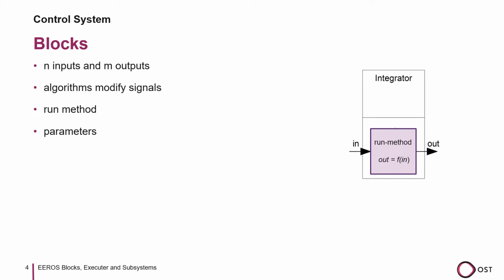The example shown on the right is an integrator block. It is often used to build PID controllers or to realize observers. Sometimes you also want to save values and use them the next time the algorithm is called. In the case of the integrator, this is the integrator's internal value. Blocks can also have methods that are called by the sequencer of the safety system. With the integrator, for example, one wants to set the initial values or stop and restart the integration. This is very important because the integrator in a controller is not allowed to integrate when the motors are switched off.